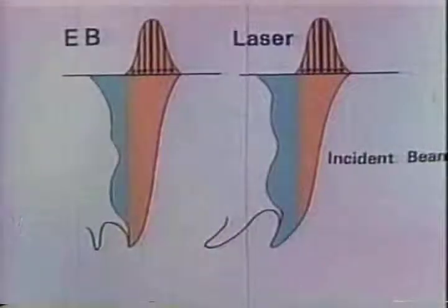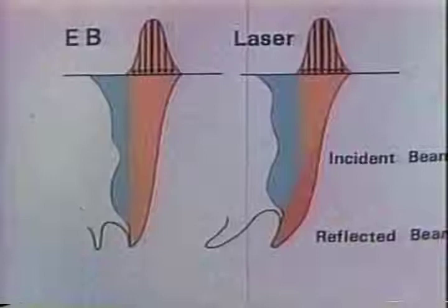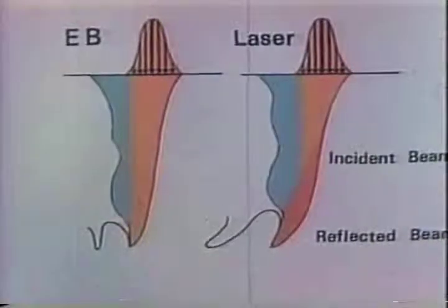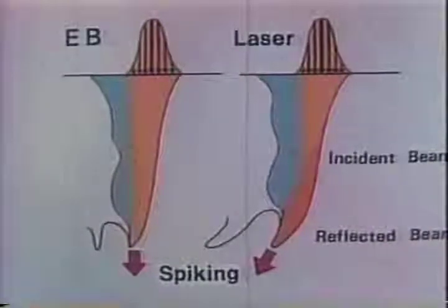This shows again the formation and motion of shoulders in laser beam welding. It is clearly seen here that the behavior of the shoulders is also related to the formation of spiking, similar to that of electron beam welding. As has been described, the mechanism of spiking is essentially the same both in electron beam and laser beam welding. The only difference is in front shapes, which comes from the fact that in laser beam welding there is considerable beam reflection at the front wall. And this effect results in a different direction of spiking in both processes.